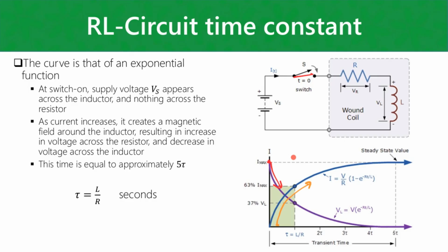So then you're going to end up with a situation where your supply voltage is essentially applied to your resistor, and your inductor is going to act like a short circuit.